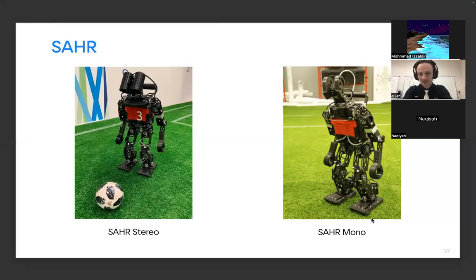It's a gyroscope and accelerometer. So the robot is understanding if he's accelerating somewhere and rotating. And also he has positional encoders in all of the servos. So he knows exactly the positions of each of the joints. And that's enough for him to plan his motions accordingly on the field.